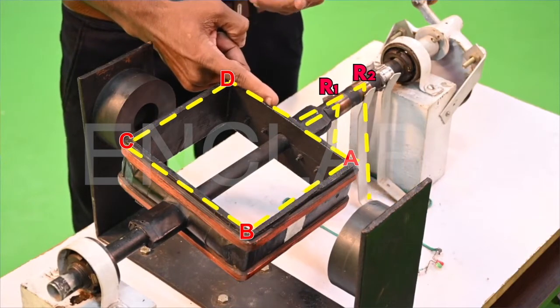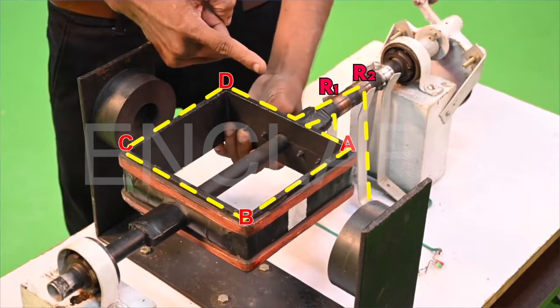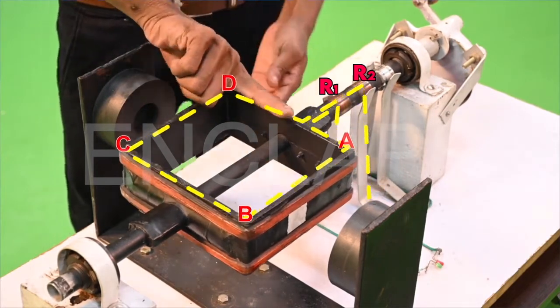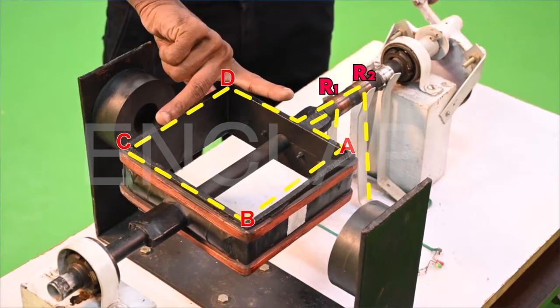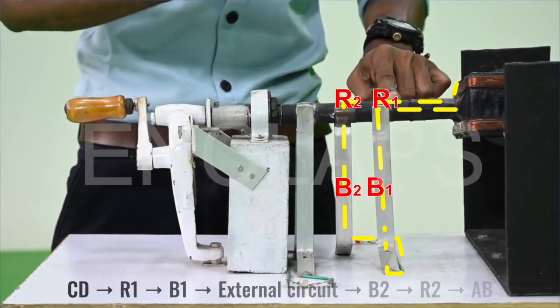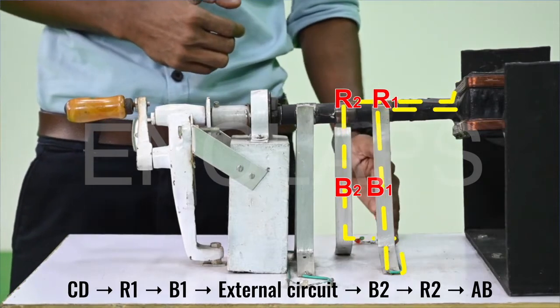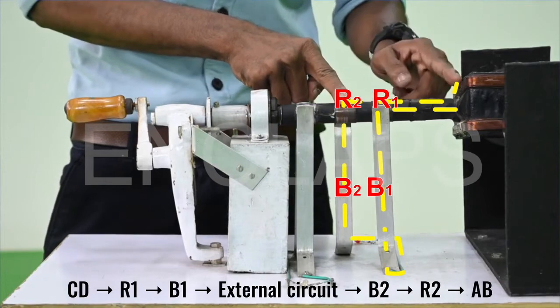The CD is rotating downwards. So, stretch the thumb downwards. Then the direction of the middle finger, which is perpendicular to both the fingers, gives the direction of induced current. That is, at this point the current is flowing from CD to the slip ring R1 to B1 to the external circuit to B2 to R2 and then to AB.